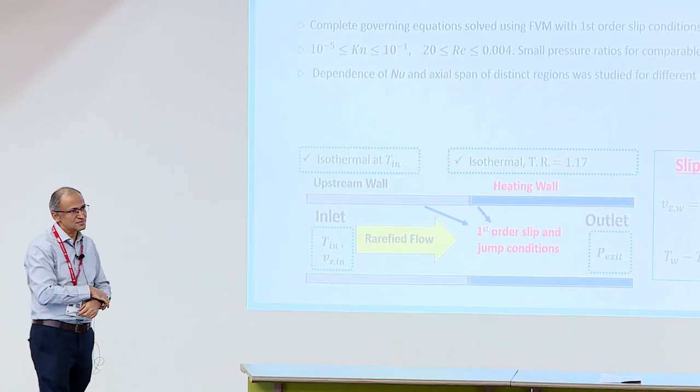And of course, Satya has done some of those works. Now, Professor Srikanth, I think he used helium, right? No, he used nitrogen, and copper tubes. Yes, copper tubes. But traditionally, in many of these rarefied gas dynamics literature, people used glass tubes and tried to measure these accommodation coefficients by looking at the pressure drop. So most of the data available is not necessarily from metal tubes.